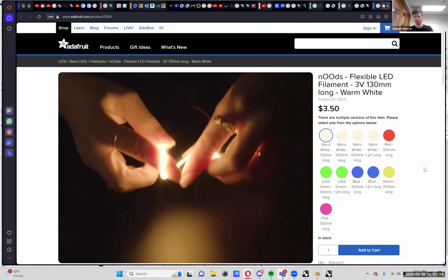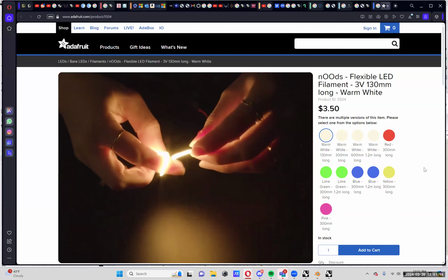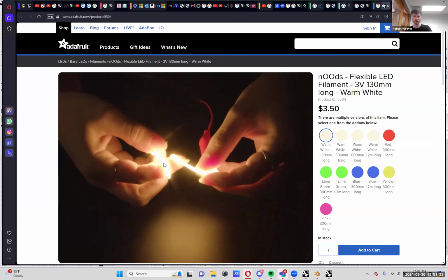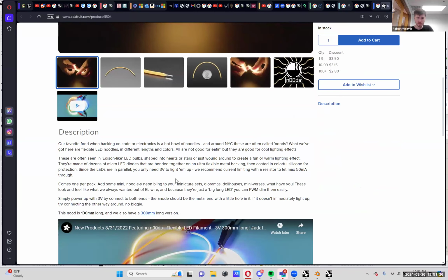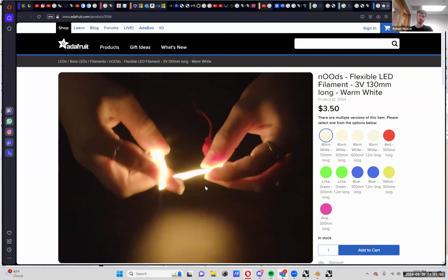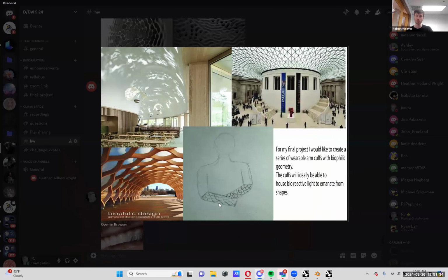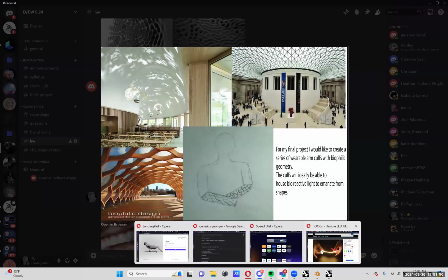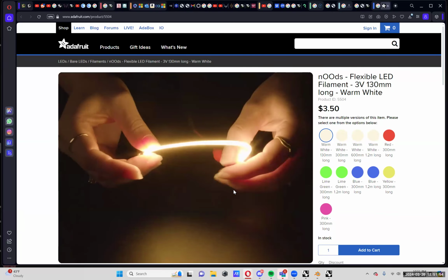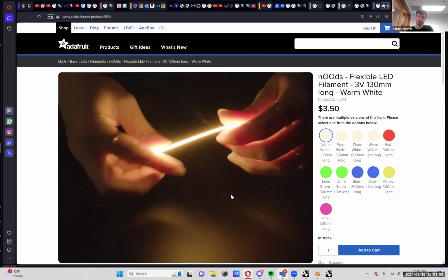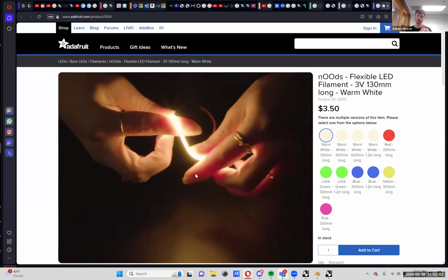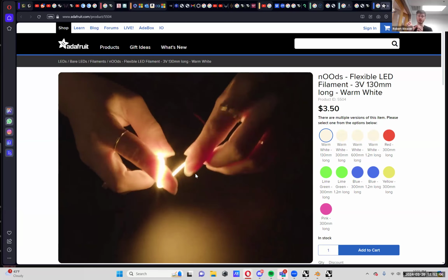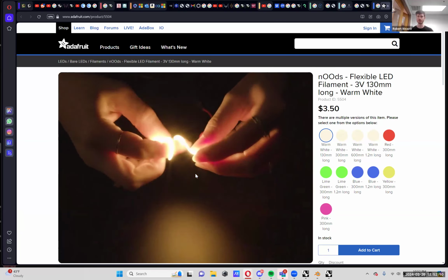Okay, so there would need to be a channel for what we're looking at right now. Yeah, you could take this wire, and I don't know exactly what the thickness is of them. It's probably listed somewhere, but you could lay down the curves that you generate in Grasshopper based on the sketch you have. You could do all these curves and do one radius for that electric wire, and then another radius for the pipe, and then use the first one to cut out the second one to have a gap in there that you could thread this electric wire through. So once again, one radius would be the shape, and the second radius would be for the pipe. With 3D printing, leave a space of whatever thickness for this electric wire, and then maybe offset it by 2 or 3 millimeters to make the second pipe, and that will encase the first one.